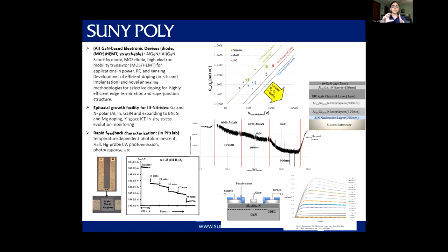So we can manipulate in situ the thickness and also the composition of these layers to achieve the type of stress we require. Some devices you actually want to have internal stress in. This gives us eyes in the system as the device structure is growing.